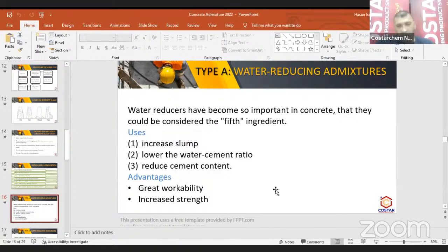In all the mix designs, when I see them, they list, for instance, the aggregate, the gravel 3/4, the half, the 3/8, sometimes the crushed sand, then the fine aggregate, then the cement, the water. They don't mention the air, definitely, or they forget about it. And then they stress on mentioning the admixture and how much it is. Now remember, guys, we said the admixture will compensate water.